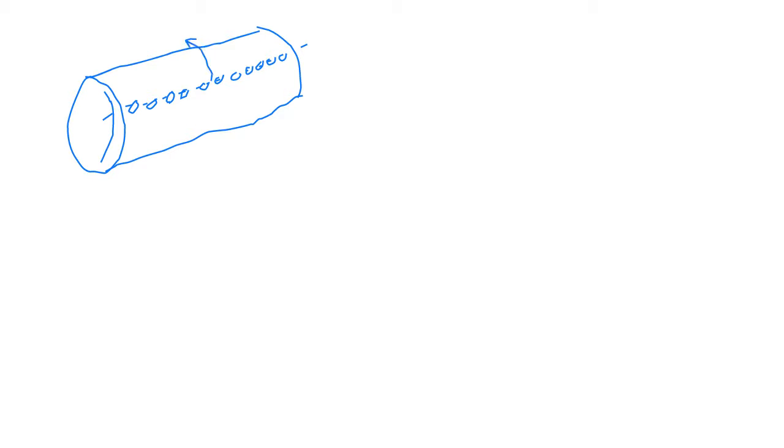So here's my circumferential stress. And the cross-section of material is much less because if I was to look at it from the side, like if I was to cut through it, I'd see a tube hole here. I see another tube hole there. Another tube hole there. And you get the idea. So instead of having full material thickness, which would give me 100% efficiency, maybe after I've drilled all the holes, I've only got 50% of the material remaining.